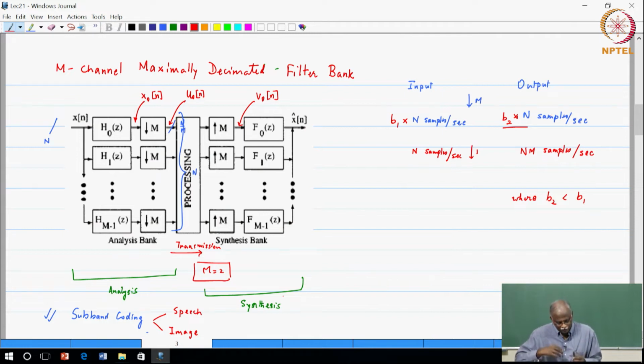So, you will lose information. So, without losing information, if you want to represent, and if the original signal was Nyquist sampled, since we do not know what the input signal is, we assume it is Nyquist sampled. Then we say that okay, the best that I can do at the subband stage is to preserve the number of samples per second, not increase it, not decrease it, I may run into trouble. And of course, then compression can happen at this rate.